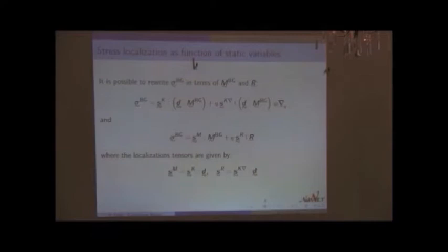There are other ways to derive this. I understand if you feel a bit uneasy with this way of introducing the bending gradient. There are other ways of doing that which are much clearer, but I wanted to keep with the asymptotics for introducing Kirchhoff-Love plate theory. I think it's very interesting also. So let's assume that I have an approximation of the stress displacement as a function of the bending moment and its gradient.